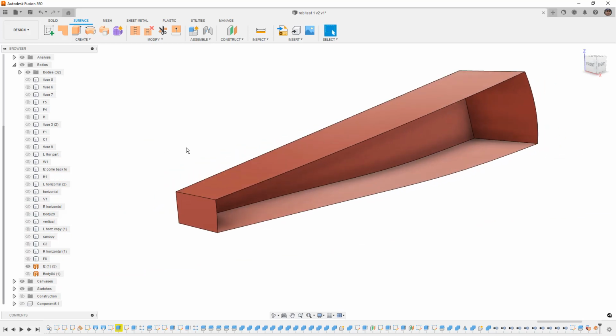So a couple of different ways that we can approach this. We can decide to loft from a start to an end, and a lot of times that'll give you that nice smooth transition. Sometimes you might find that the loft control isn't quite what you want, and you might want to go in and actually build it out a little bit differently, and you can certainly do that.